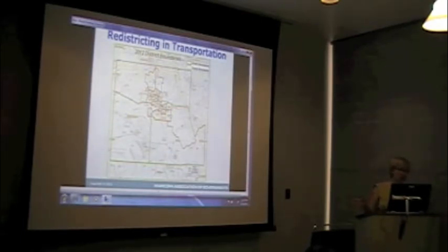So if you are to do this type of work, you need to figure out how you make the decision to draw the boundaries, because the boundaries have a big impact on the output. If they're not done well, you can skew the result, like cause the model to underperform, underestimating future traffic, or overperform, giving too optimistic estimates of how good of an investment it would be if we, say, build a light rail.